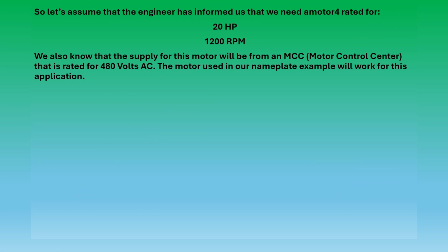So let's assume that the engineer has informed us that we need a motor rated for 20 horsepower and 1200 RPM. We also know that the supply for this motor will be from an MCC motor control center that is rated 480 volts AC. The motor used in our nameplate example will work for this application.